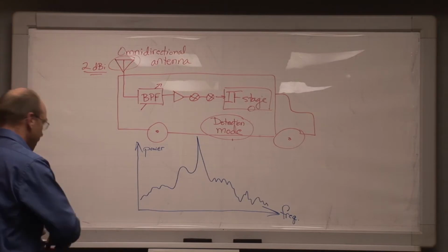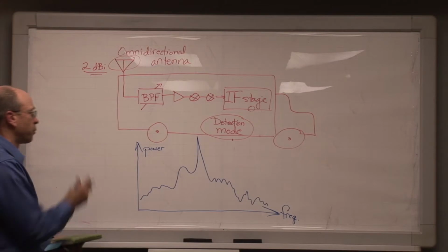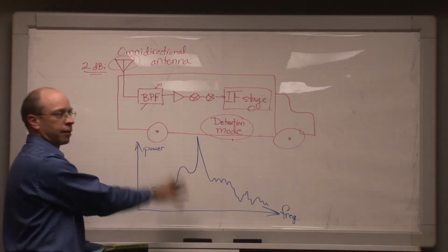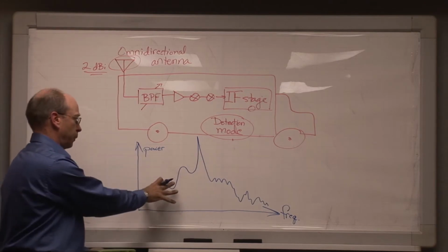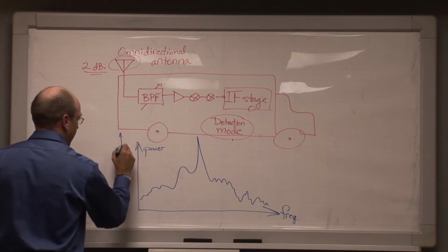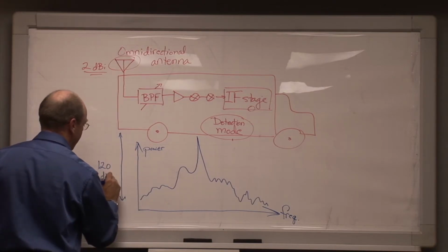And the goal here is to first of all measure the spectrum with as much dynamic range as we possibly can get, because we may want to have this in our catalog at NTIA for later use for other purposes, but if at all possible, we're going to try to get 100, 110, or even 120 dB of dynamic range.